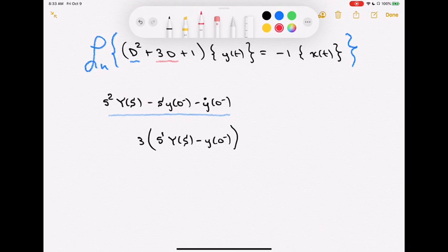So I'm using the derivative property of the Laplace transform as well as the linearity property of the Laplace transform. And so I get some terms in there as well. Remember, these guys are getting all summed up. The last one is just the Laplace transform of the signal by itself, y. So we probably don't need another line for that, so I'm going to go ahead and put Y of s. If I wanted to color code that, I could do that as well. So we know there's that term 1, and we end up getting this piece over here, Y of s. I now need to transform the other side. The other side is an easy transform as well, because the input here is just so trivial. It's minus x. So the unilateral Laplace transform of minus x is just going to be minus capital X as a function of s.